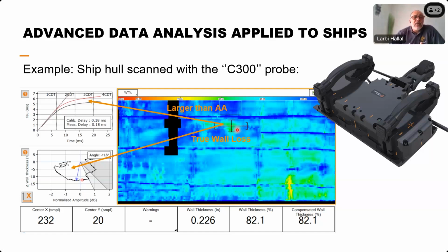If we look here, this is seen, looking at the Tau-Scan curve and the PermTool, as a real defect. So this is not material property variation. Here we have, as we have seen before, on the plateau, bending region and infinite wall, bending and plateau region, a nice A-scan signal typical from a wall loss. And when we look at the PermTool, most of our signal is plotted in the undefined region. So calling a corrosion here can be done with confidence.